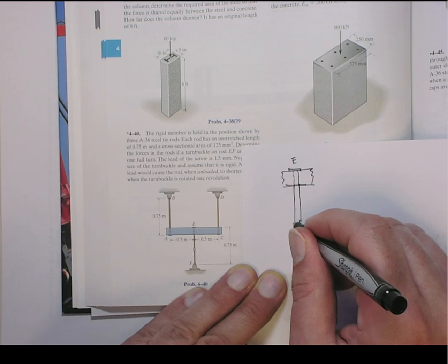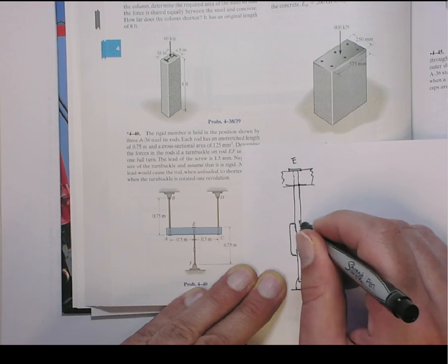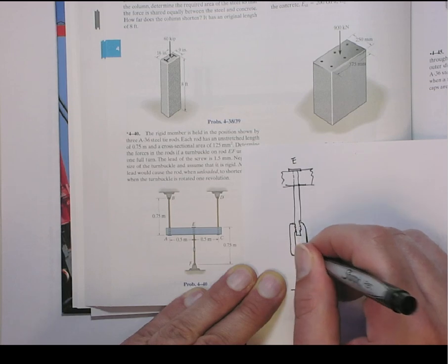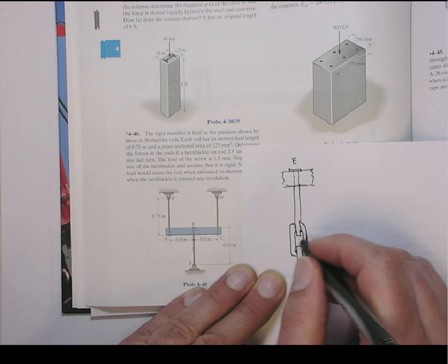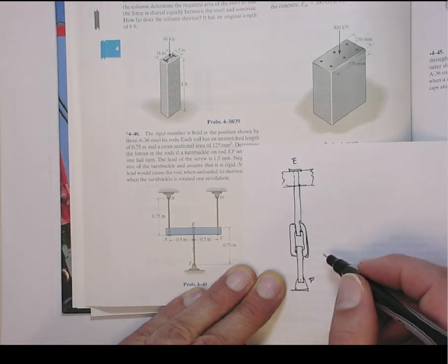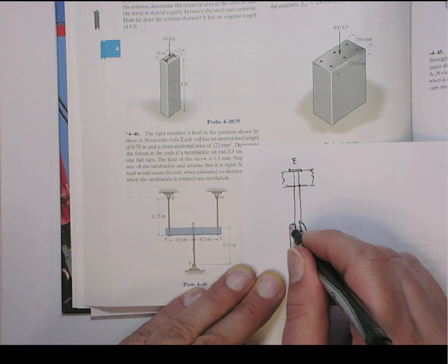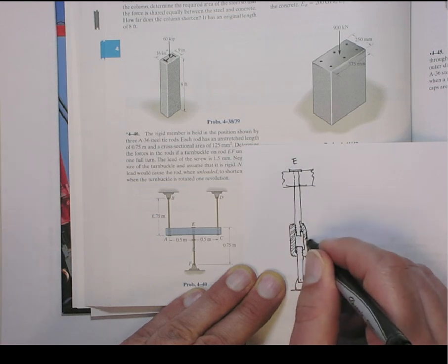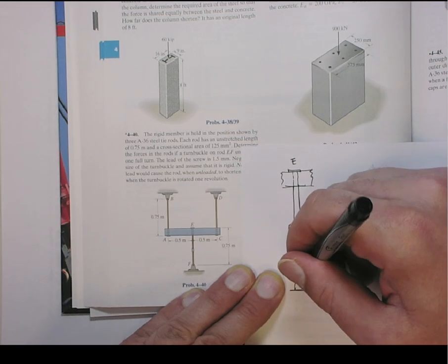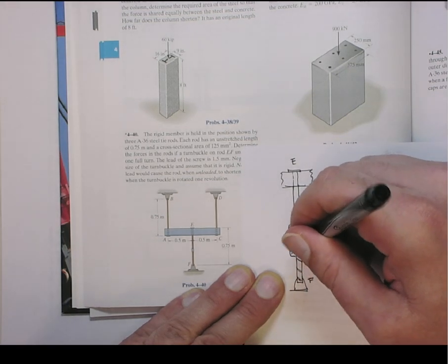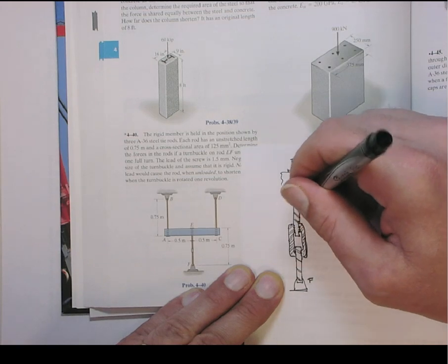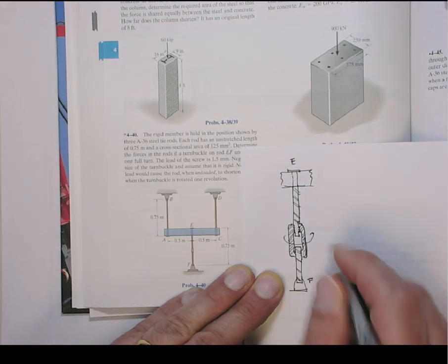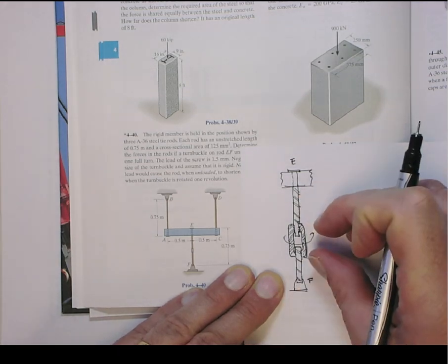And then we have a turnbuckle here, which, if you've seen those things, I don't know if I'll be able to draw it nicely. It's kind of like a hollow tube with a mating thread. Let's look at a cross section. This is the turnbuckle. It connects these two rods. As you turn this, it pulls these together or pulls them apart depending on which way you turn it.